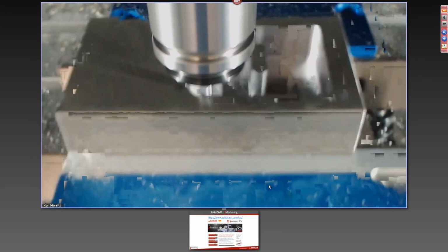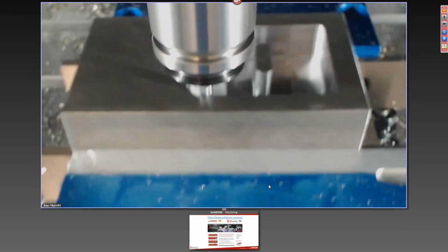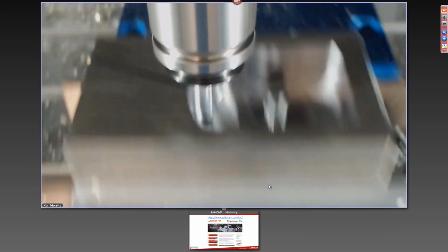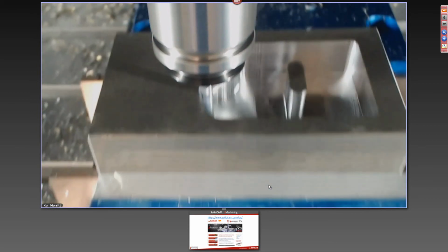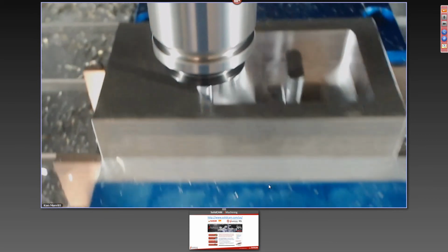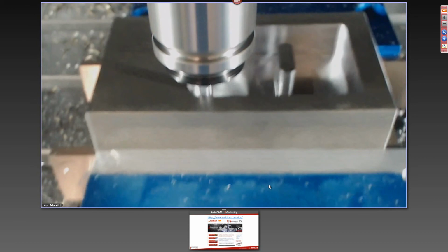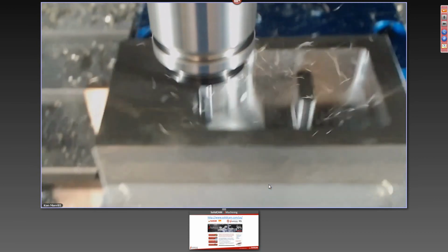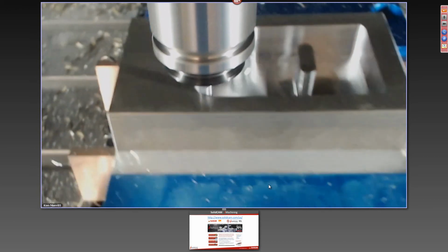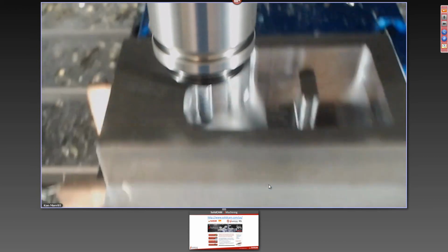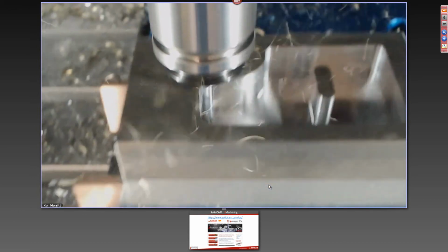Now, you saw that go through some morphing spiral. Now it's doing the D-slot trochoidal. These are the parallel offsets, because it could not machine all of this material out within the min-max parameters that I set for the cutting angle. But now it's getting it prepared so it can return to the spiral morphing, and you'll see that in just a moment.